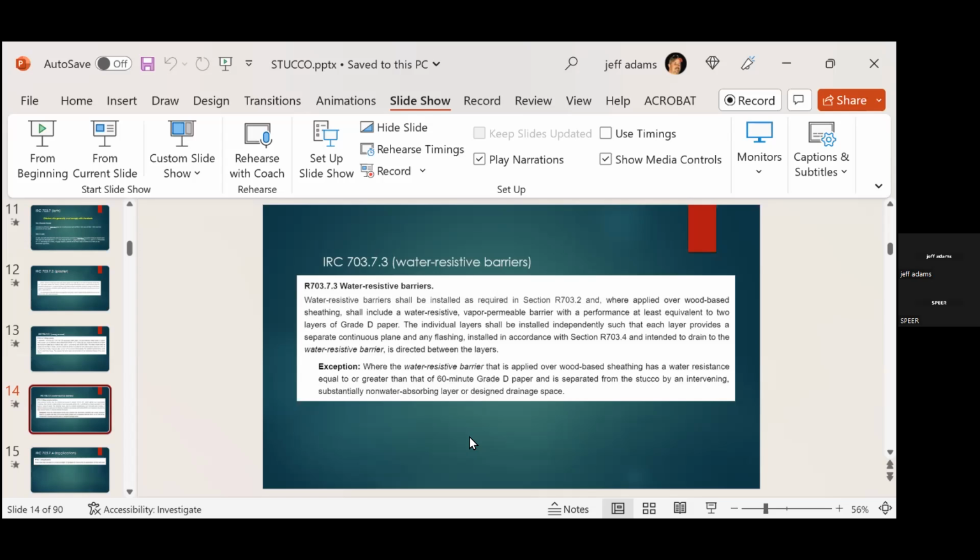And hopefully more cities will start getting involved in doing WRB inspections. A lot of cities are not doing them, but it's very important no matter what material, whether we're talking about brick, stone, fiber cement, an LP product, wood, cedar, lap. I mean, it just doesn't matter. It's all about these WRBs and these flashing details at the windows that is what's going to protect these houses.